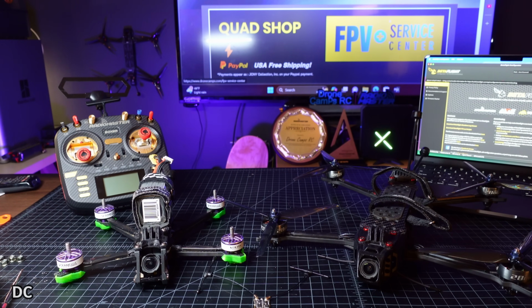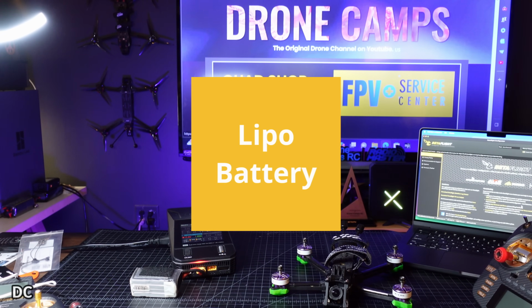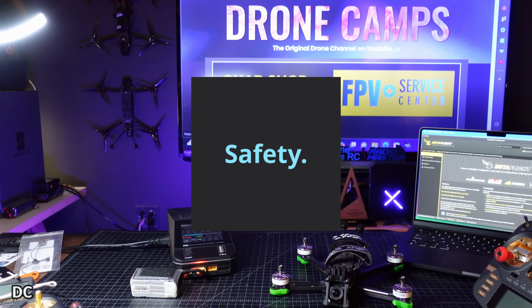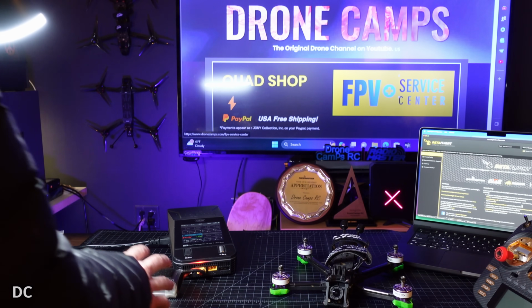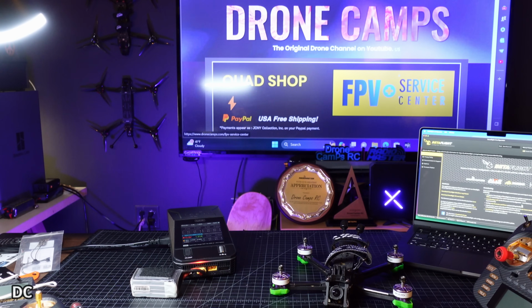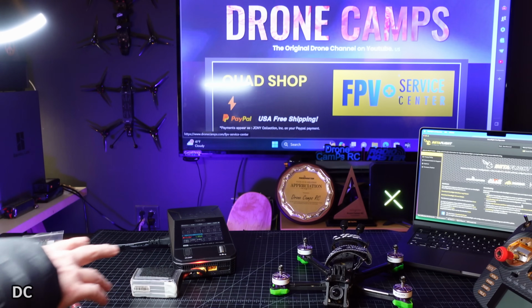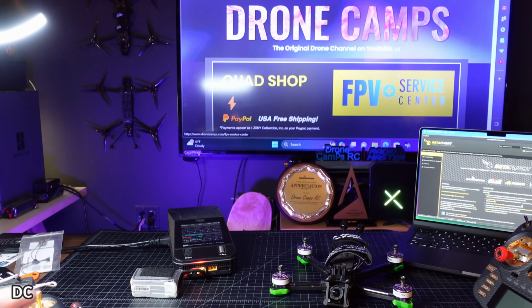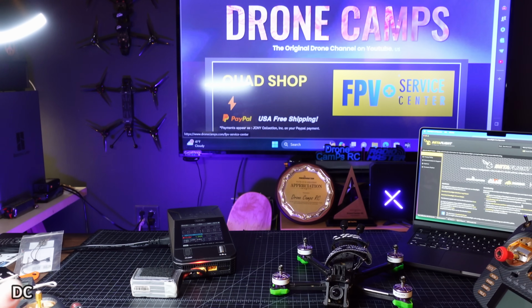Now, our next tip for beginners is LiPo battery charging. The most important thing I can tell you about LiPo battery charging is do not leave your battery charging by itself. Don't leave the room that you're charging it in. Don't get in your car and drive down the street to go get a drink or anything. Don't leave your house and come back and just hope that this is finished later. Sometimes I've had friends who had these explode on the bench. They can cause a fire in your shop. They can burn down your house.